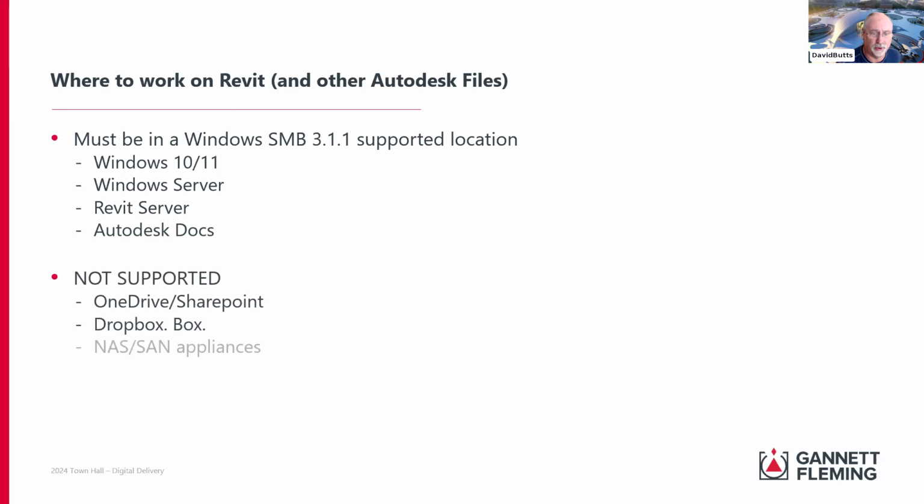What is not supported for you to host and edit Revit files? OneDrive, SharePoint. Don't even put your AutoCAD. You can share files up here, but don't edit files from up here. And I saw Tony earlier had a path to a Dropbox location. You can only do that when you're the only person working on that file. Then you can do that because nobody else is going to be able to access that file if you're the only person that has access.